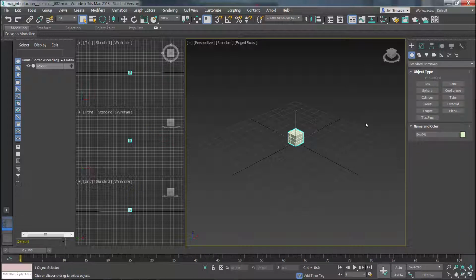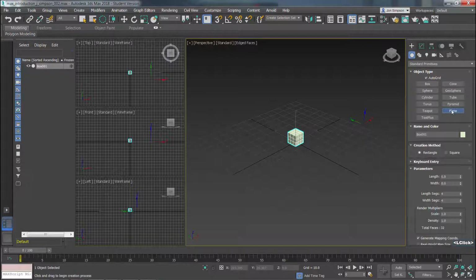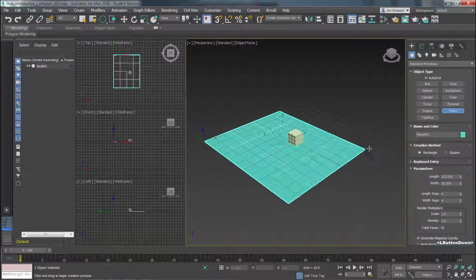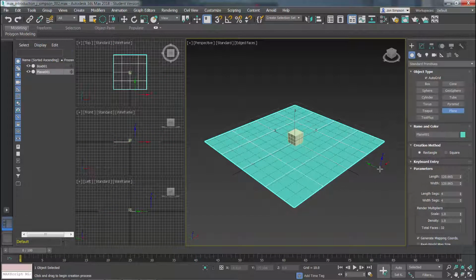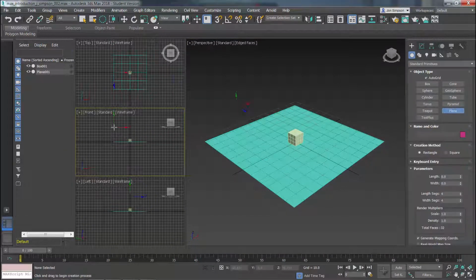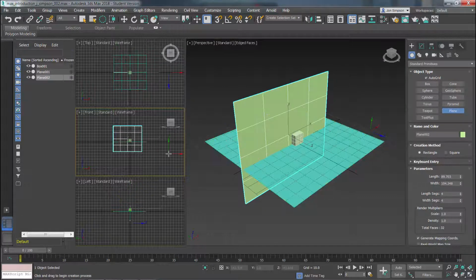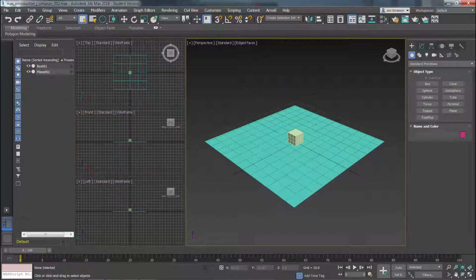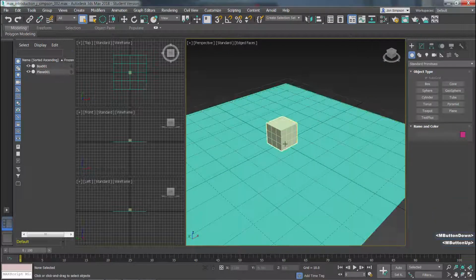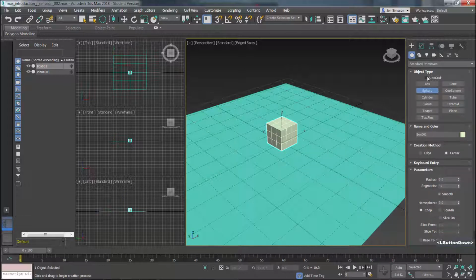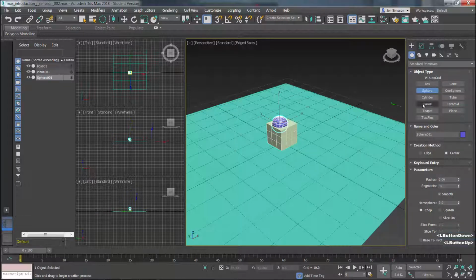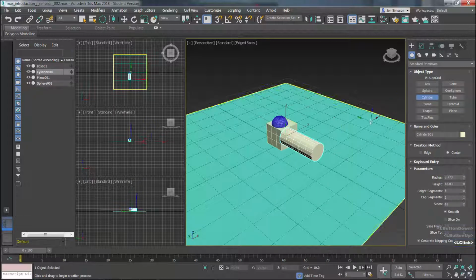Additionally, select the object to be created, then click and drag in a 3D viewport. The object will orient itself to the viewport it was created in. The outside of the 3D object is made up of faces, also called polygons. Autogrid is a toggle that orients a new object to the face it is created on.